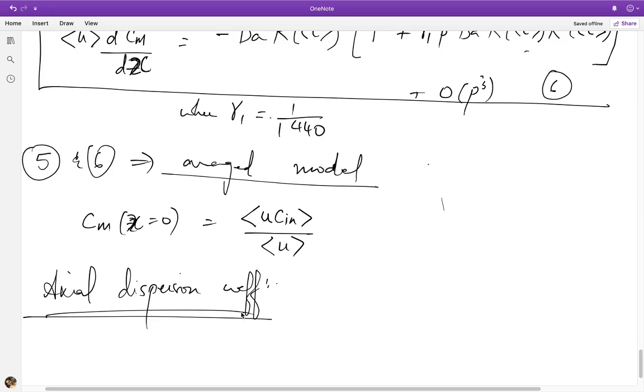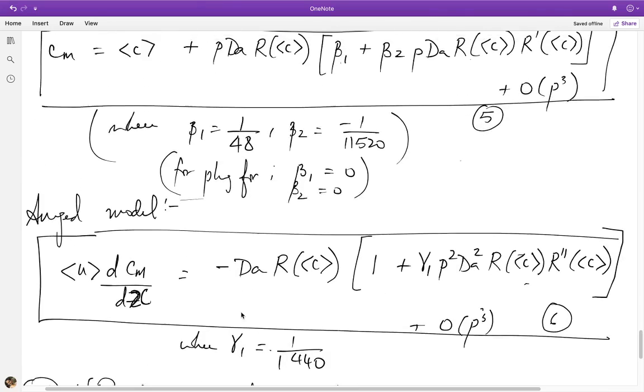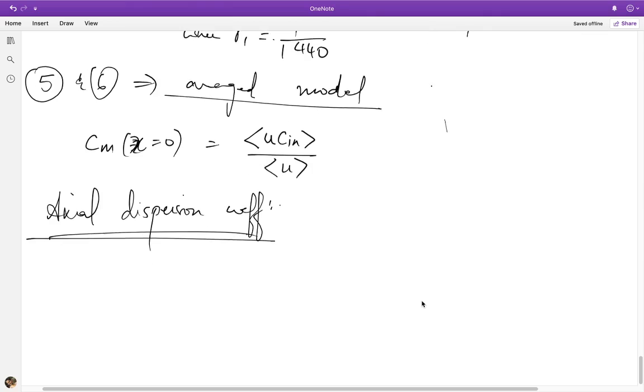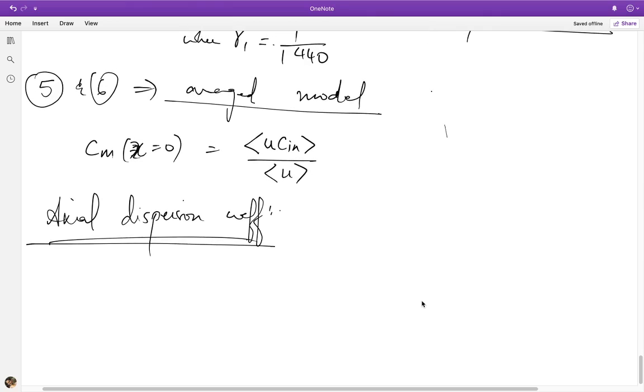Okay, so remember in the previous lecture we derived something similar to this model, and what we then did was substitute C bar in terms of Cm, or vice versa, into the right hand side term, and we got an effective single equation which had an effective diffusion term. So you will get d square by dx square times the coefficient, which is what we interpreted as the dispersion coefficient. We can do the same thing here, although it requires some more algebraic manipulations. I shan't go into that. Instead, I'll just give you the final result.